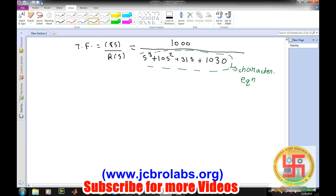Now, as we said, we create a Routh table, so we'll now understand how to create it. In order to create the Routh table, we first take the coefficients of the highest power of s. The highest power is 3, so we take the odd powers from the highest power towards 0: 3, then 1.